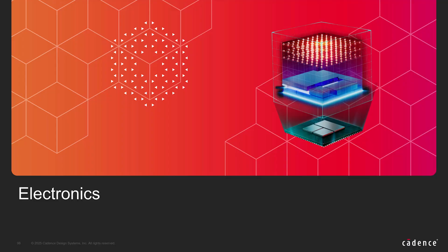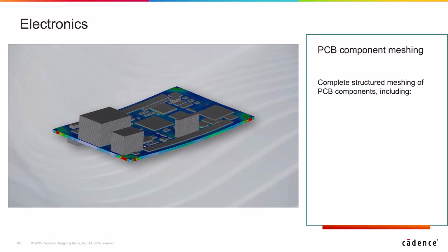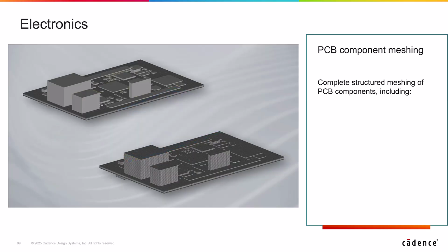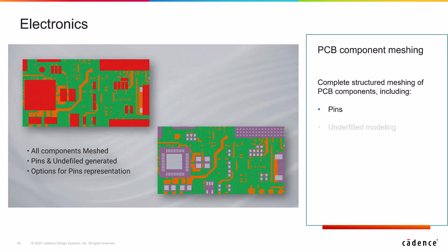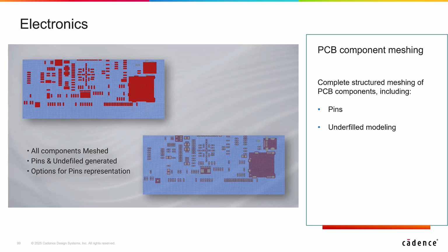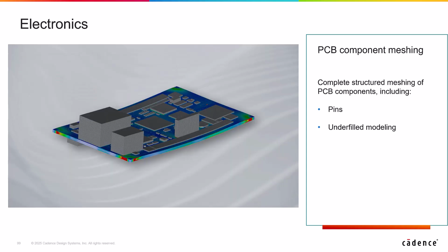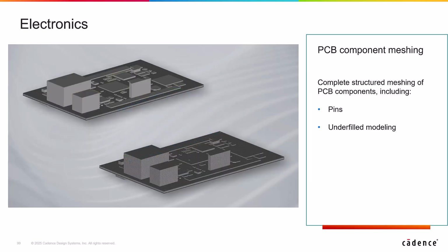Moving on to electronics. Based on the output generated by the ECAD importer, a dedicated tool has been developed to mesh all PCB components and accurately represent pins, underfill, and solder mask. Upon completion, the PCB is fully meshed using a highly structured mesh, ensuring detailed and precise modeling.